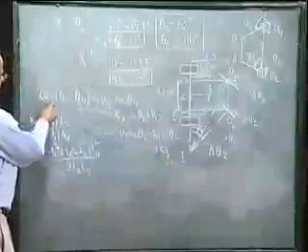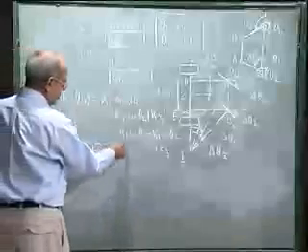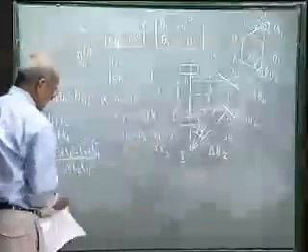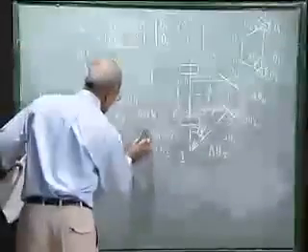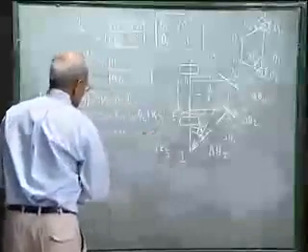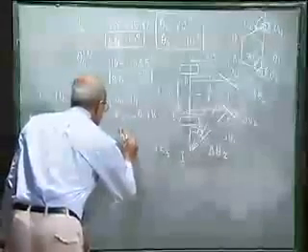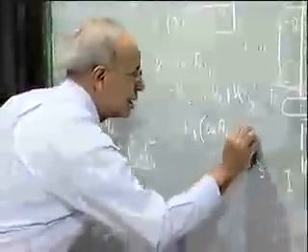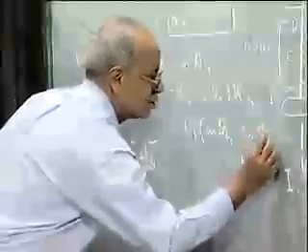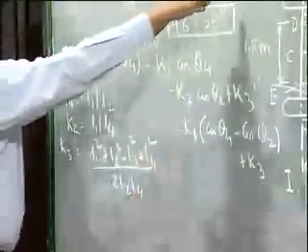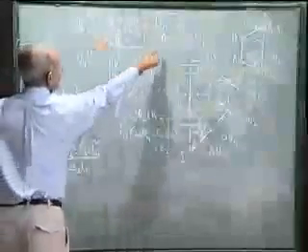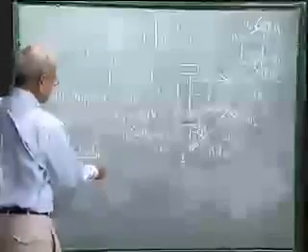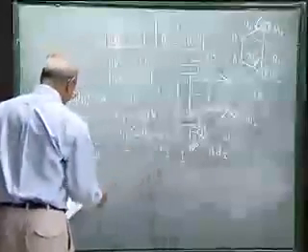So this equation, cosine of theta 2 minus theta 4, K1, if I take common, I can write it as K1 times cosine theta 4 minus cosine theta 2 plus K3. And these two pairs of movements have to be satisfied by this equation. So if we substitute, we get two equations to solve for K1 and K3.